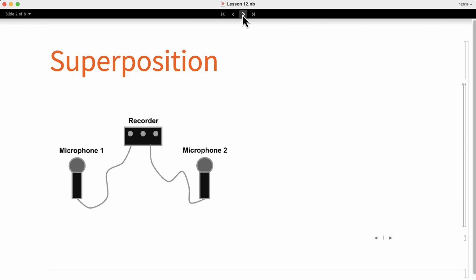To give you an analogy, when recording this video, I'm speaking to a microphone and recording the audio that you are listening to. I could give a second microphone to another person and record this person speaking. At the end, we can mix the audio signals, and when played back, it will sound like we were in the same room. When using superposition, we can analyze a circuit one source at a time, and then we can combine the results to obtain the final result.